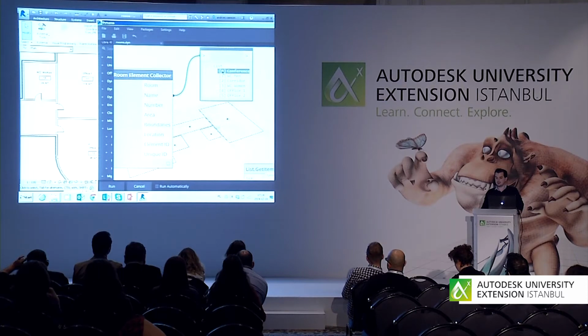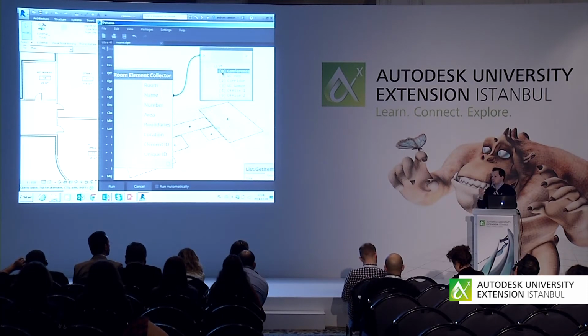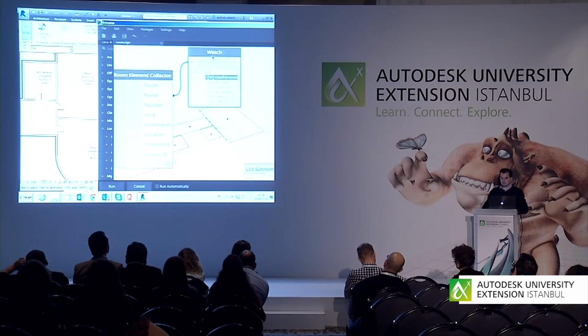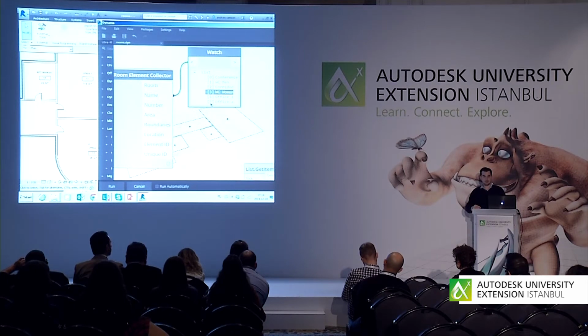the conference room has, so imagine that I have a big building and I have 100 different rooms, okay? And if I want to automatically iterate or select amongst them, I need to tell the computer, or tell Dynamo, that I want the conference room and not a corridor, okay? And to do that, I'm using these numbers at the beginning because, as you probably noticed before, every element on the list has its position named by an index, this index in the square brackets, okay?